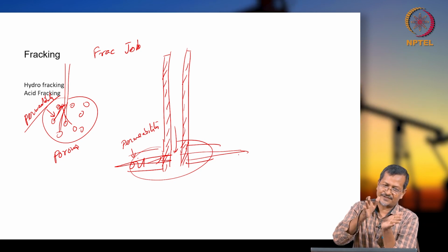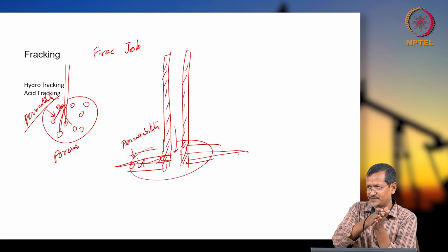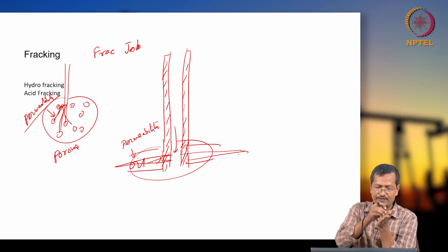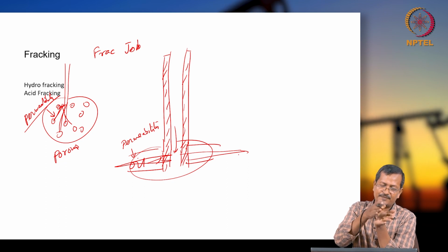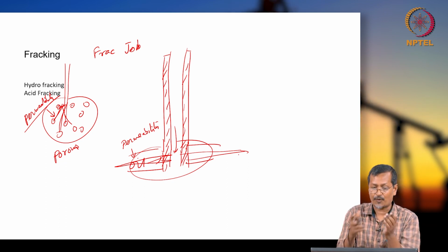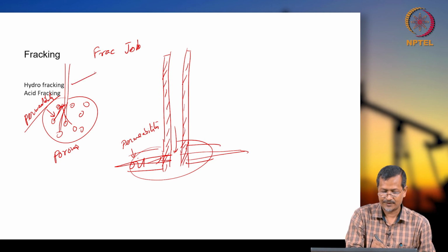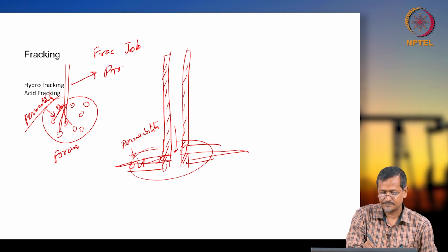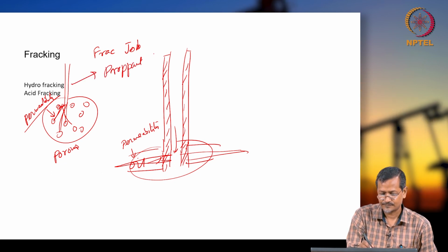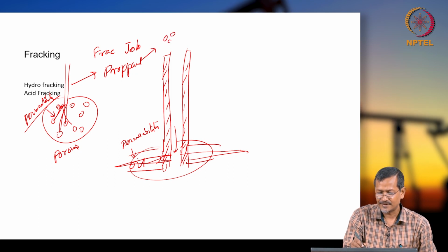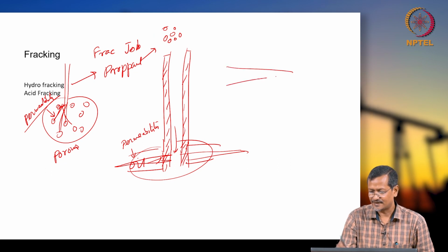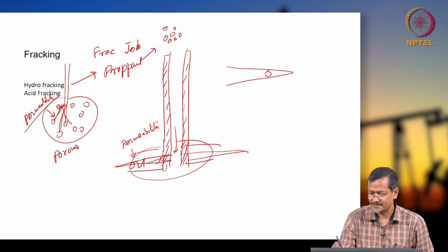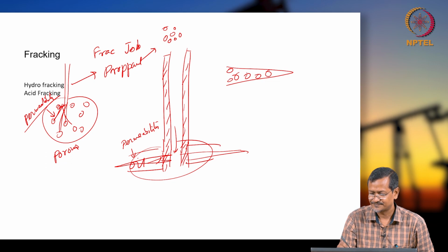So when fractured and closed, again you are not getting production actually, because when oil and gas will be moving, it needs some space. Okay, so to create space, sometimes they will be putting some sand particles, they are called proppant. In hydraulic fracturing, you put proppant, or properly sized sand particles, gravels. You create cracking like this, then you put lots of sand.